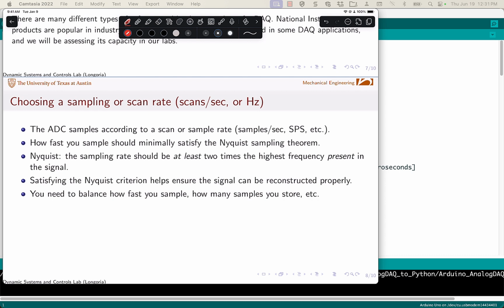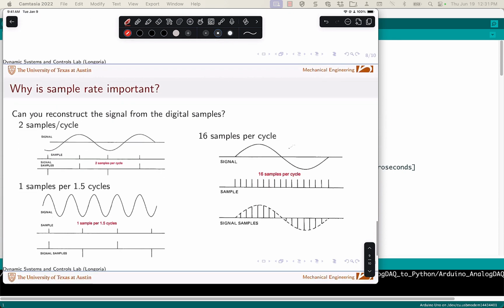This is a slow moving pendulum, about a 1 hertz natural frequency, so we don't have to sample that high. In terms of frequency, 50 hertz is what we're going to be using, and that's way high enough. There might be some noise on there, but not a whole lot, so we're not going to care about resolving the noise. But sample rates are important.